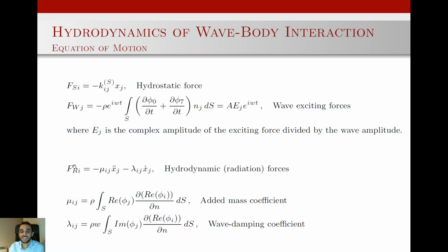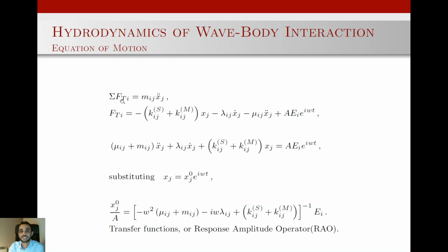And we have the radiation forces, sometimes referred to as hydrodynamic forces, which are due to the added mass, the mass that is accelerating due to the motion of the object, and due to the waves generated by the motion of the structure, which we refer to as wave damping and added mass.